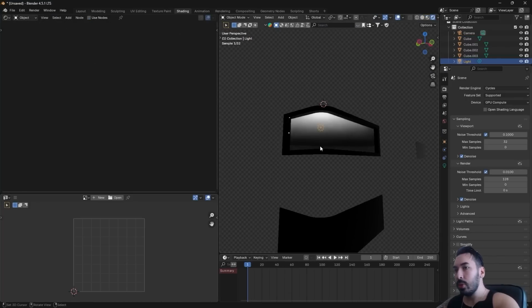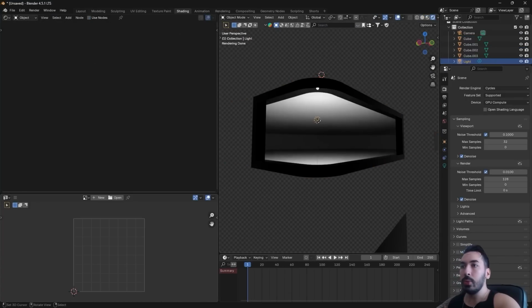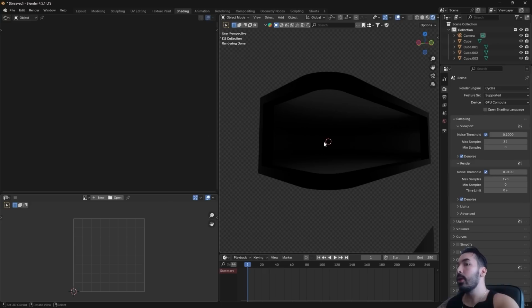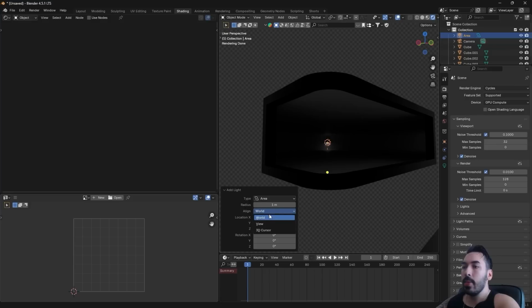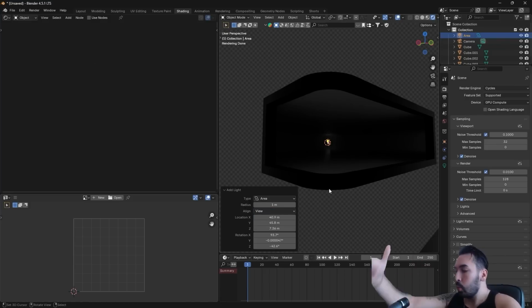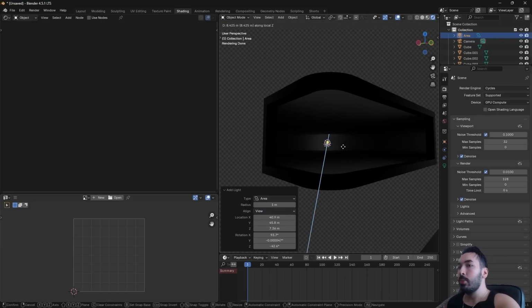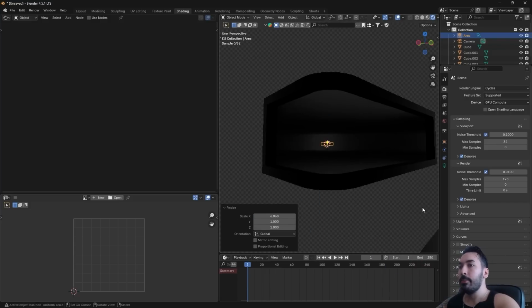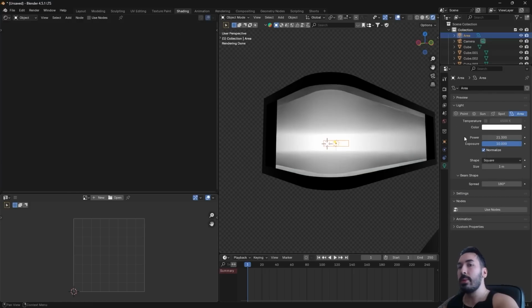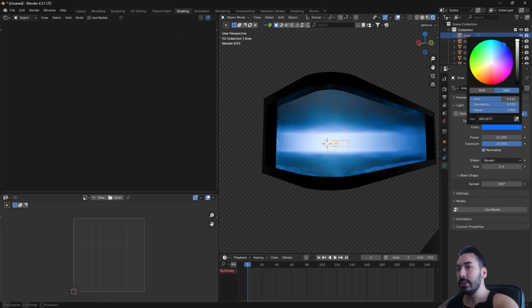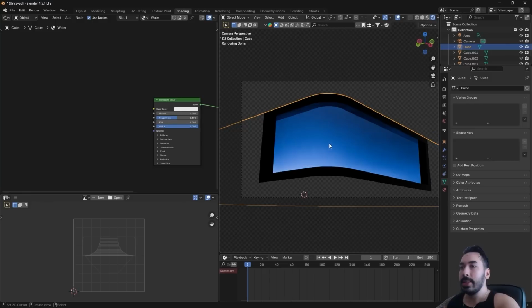And before we continue, we got to set up the lighting a little bit better. So get rid of this default light here, and we're going to click on that wall in the back to place the 3D cursor there, and then Shift A, add a light, add an area light. In the add light menu, align that with your view so it's facing that way towards the wall. Use G and double Z to pull it backwards a little bit. We can also scale it up a little bit. And now of course we're going to turn up the power because otherwise we can't see anything. So let's do something like this for now. We're also going to make it blue because that looks a lot more beautiful. And now we got the lights looking nice and cute.